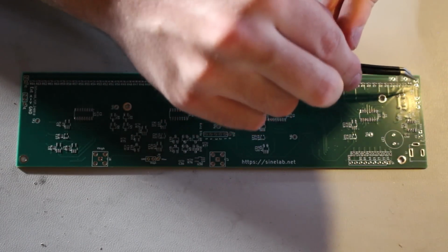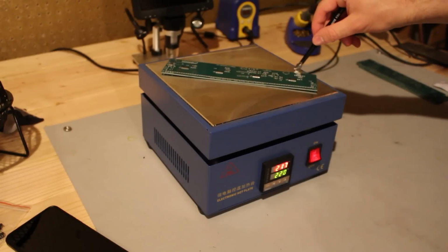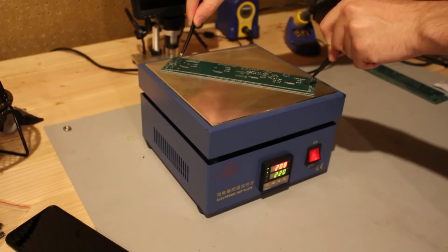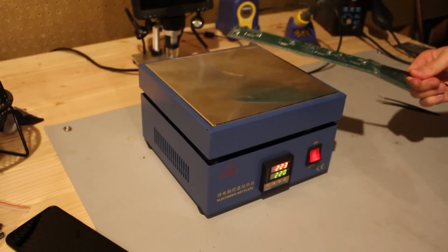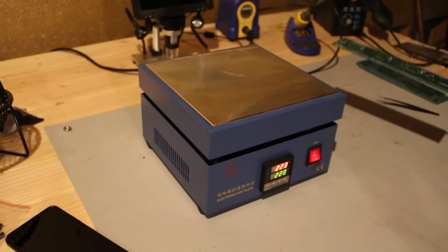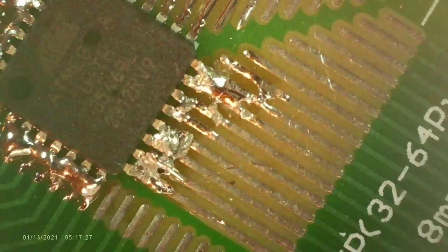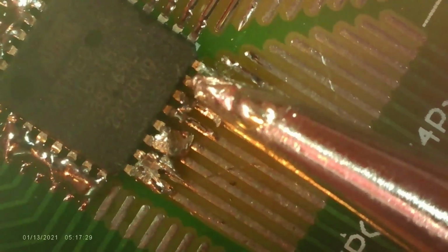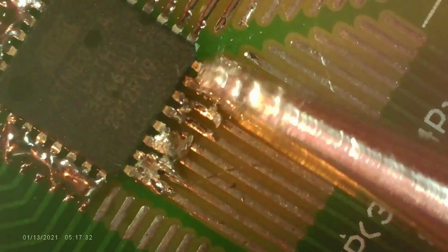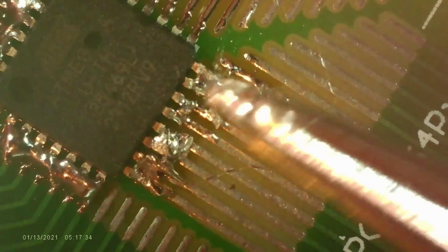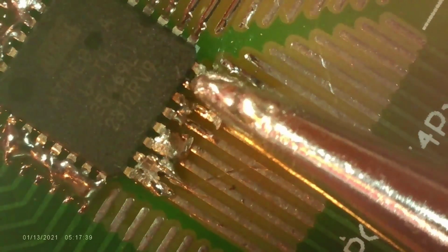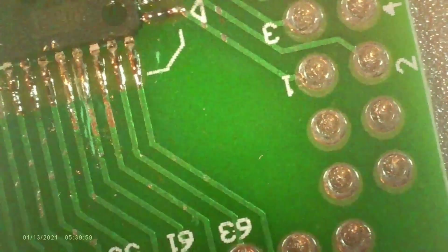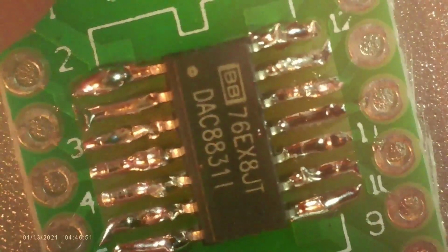Once that was done, I placed the board on a hot plate. For these larger boards, I recommend holding them down at the corners to ensure even heat spreading. Unfortunately, I can only use the hot plate method for the top of the board. For the bottom, I had to hand solder it all together. Having this microscope helps a lot with the SMD hand soldering, but it's also definitely doable without one. Just make sure that you aren't accidentally shorting pins together, especially on these really finely spaced pins.